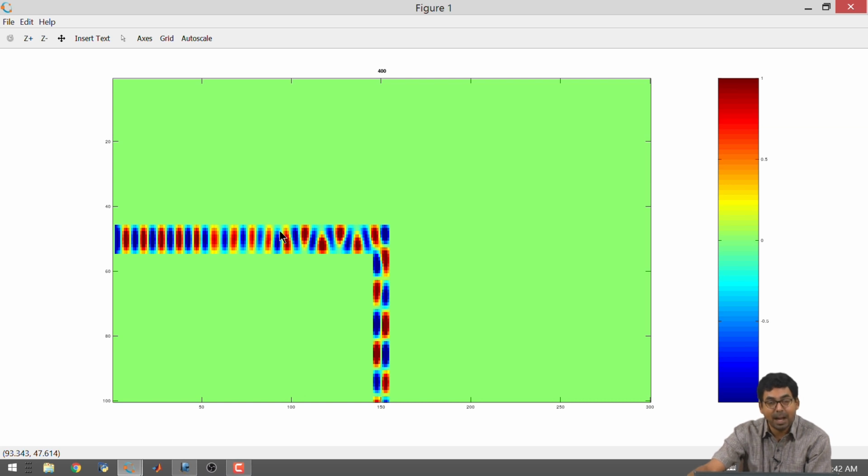All right. Whereas the higher order mode, all right, is actually doing something different than the fundamental mode. Maybe it's doing multiple bounces and the way it is traveling is very different from the fundamental mode. All right. And it's also clear that when you had an abrupt bend, the higher order mode passed, the fundamental mode did not pass over here, right. So, these are all some things that we have not studied analytically, but this program now gives you some starting point to make experiments with structures and try to see what all things can happen.